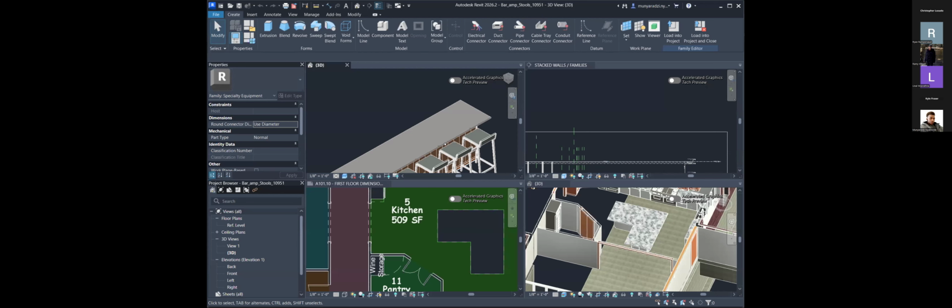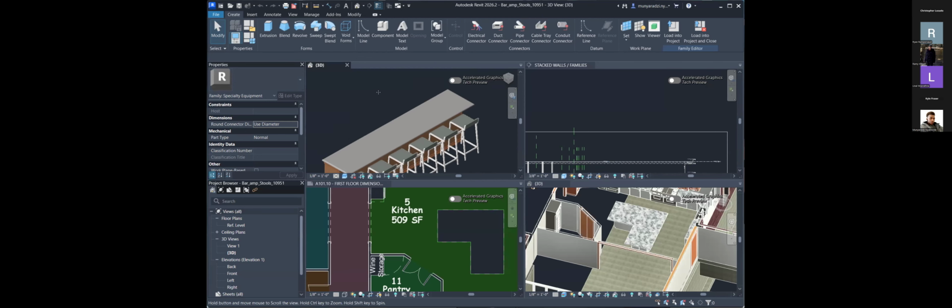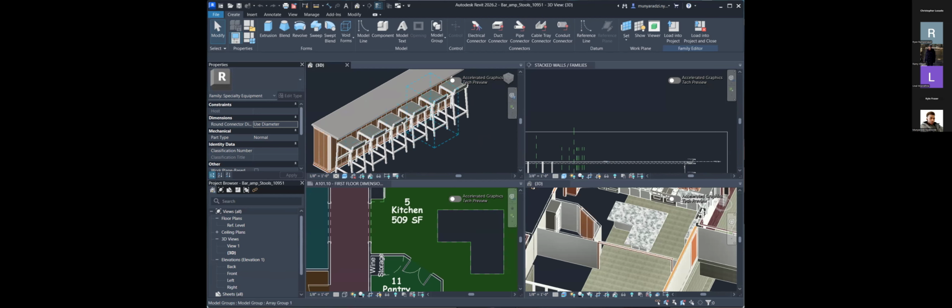Okay, so my issue is I opened up the website you were talking about, Revit and City. I found this. I want these tools, but I can't get them individually. It brings the whole table with it. Okay. And you want to get rid of the table and you only want one chair. Yeah. All right, so what we're going to do is we're going to edit the family. So double click on any part of it.